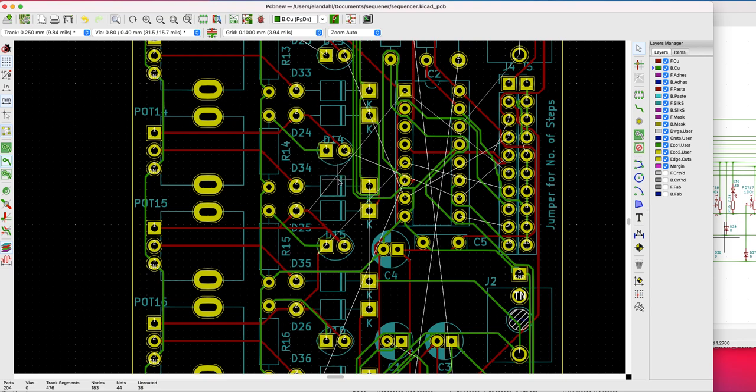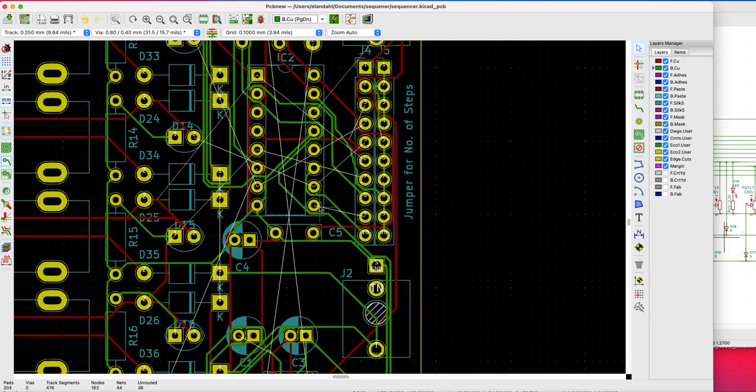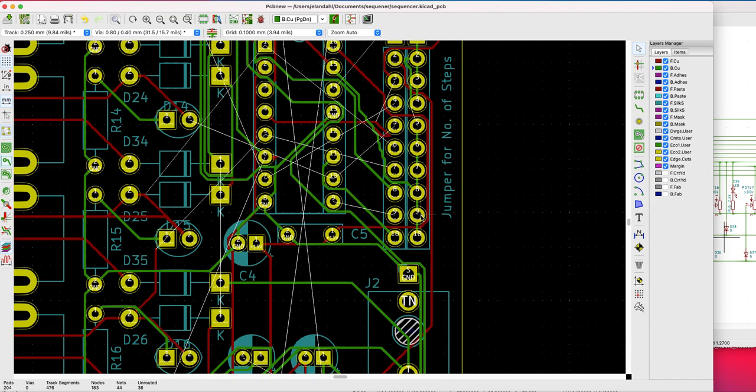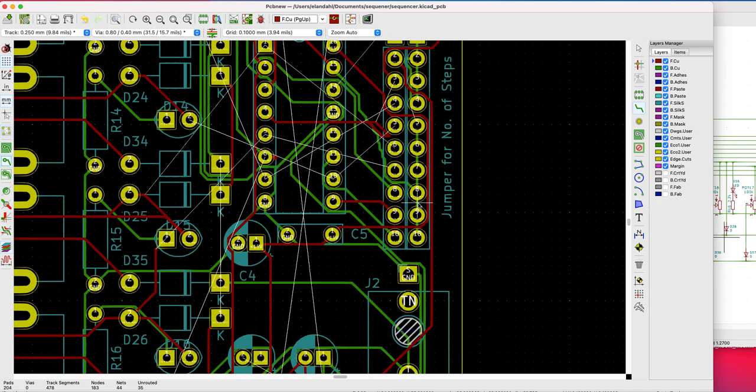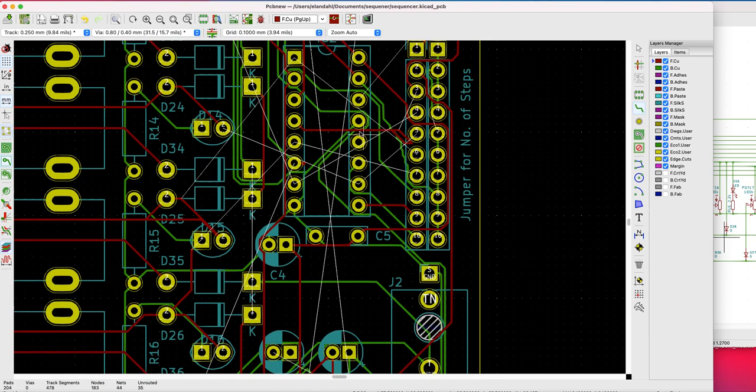So let's try to pick a couple vias here. Here actually looks to me like a wire which, after we've cleaned things up, maybe we can complete now. So let's take the low-hanging fruit while we can. There's only one crossing from pin 9 to pin 9 here, and the jumper. Let's try to do that with a top layer. Beautiful. Got rid of one. So we might be able, now that we've cleaned up some of the messes, to find a few more that we're able to actually do.